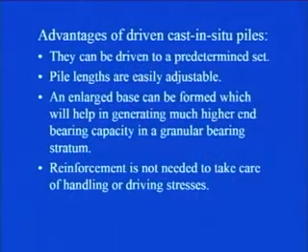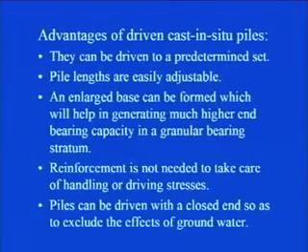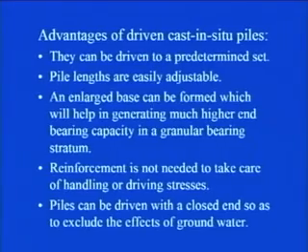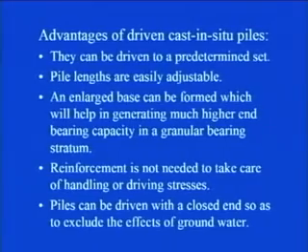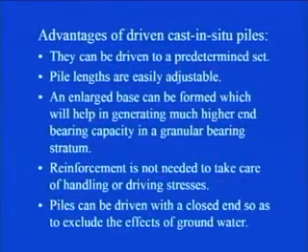In this case reinforcement is not needed to take care of handling or driving stresses. Piles can be driven with a closed end so as to exclude the effect of groundwater. Let us say that while driving the pile you come across the groundwater table. If the pile is driven with a closed end, you will not have any effect of the presence of groundwater table.